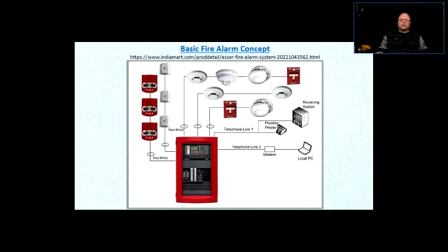When you're talking about places like furnace rooms, right close to the furnace, and sometimes really above that, there would be something called a heat detector, because heat would arrive first, then the smoke. So it would be more efficient to put a heat detector there, and the heat detector triggers upon a certain amount of heat that is surrounding it.